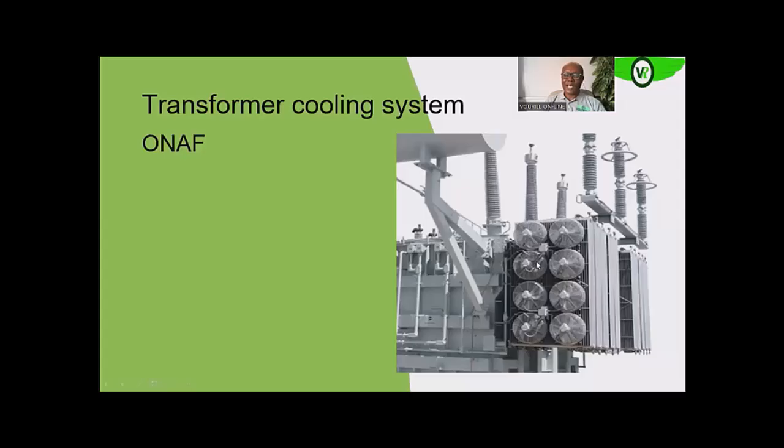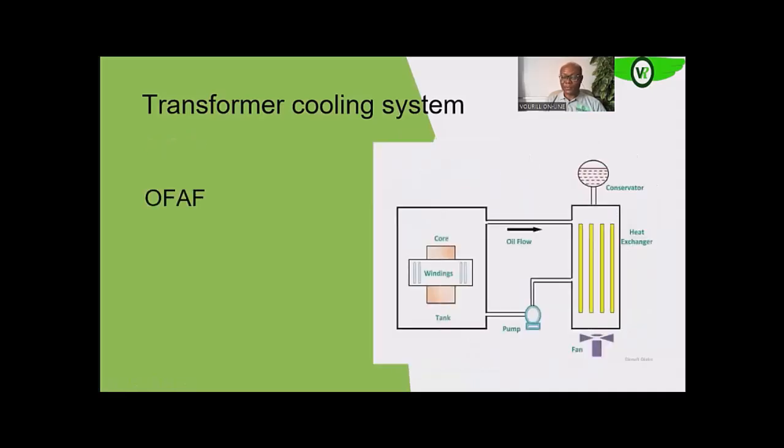And then the air outside is forced through the fins of the transformer radiator, or the cooling fins of the transformer. So this kind of cooling is known as the oil natural air forced, because you are forcing the air, okay. So there are others where we may need more effective cooling, which means we may need to force the oil, okay, through the oil pump.